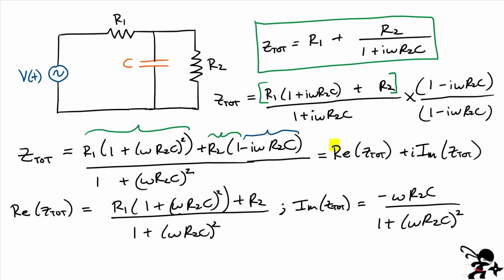We have our impedance. The reason that you want to do this is because it makes calculating the phase angle very, very easy if you have the real and the imaginary part just split up nicely. And in this case, it's messy, but it's still doable. Okay, now let's go ahead and substitute our values and see what we can calculate now with our more simplified circuit.